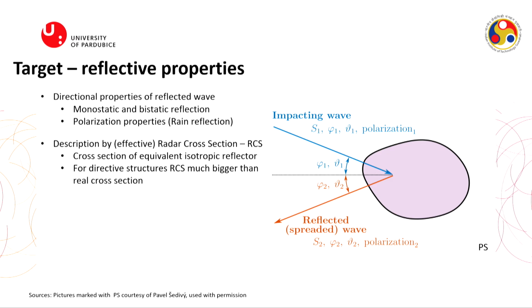It is important because when I present results from our measurements, I always have vertical, horizontal, and cross polarization. I will show you later that cross polarization almost hides any reflection from a wind turbine. That is not good, so we use vertical or horizontal.